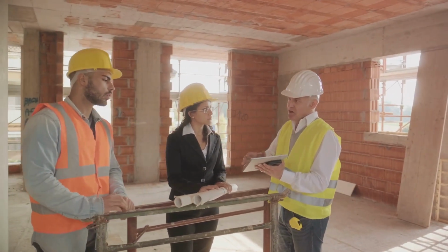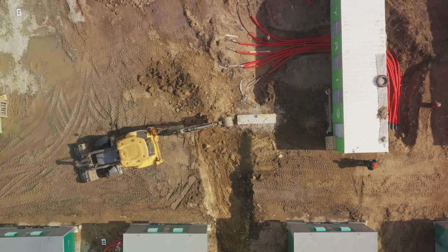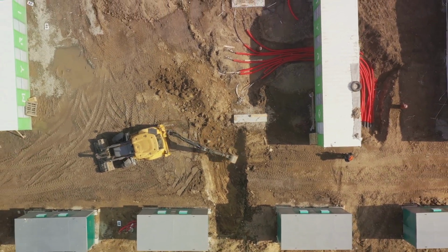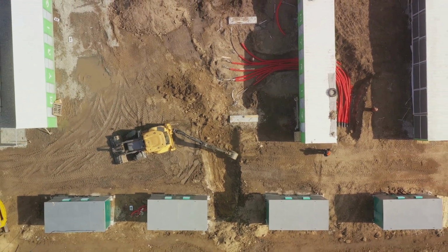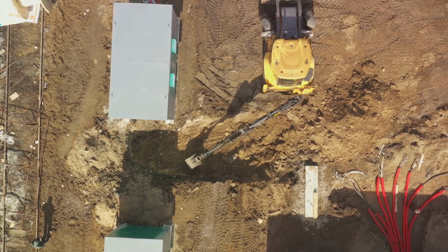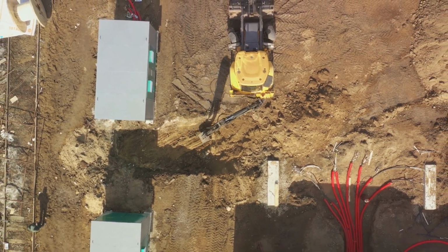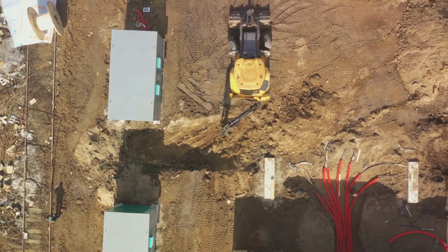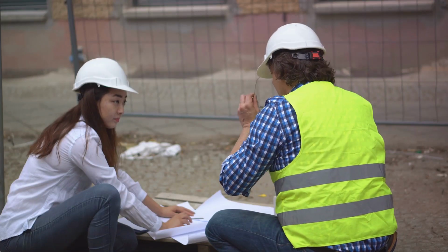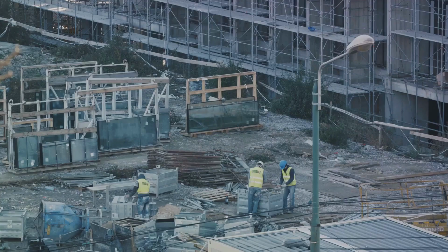And then there's the arranging of utilities. This includes setting up temporary electricity for the site, arranging for water supply, and ensuring there's a proper waste management system in place. This is another successor activity to excavation, and it too can happen at the same time as the other tasks. This is the beauty of multiple successor logic. It allows for multiple tasks, all successors to a single predecessor, to occur concurrently. It's a way of maximizing efficiency and productivity.